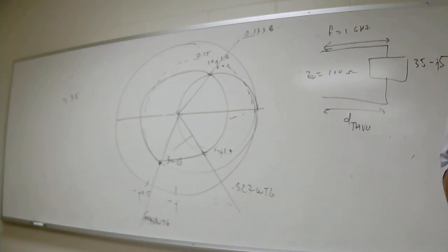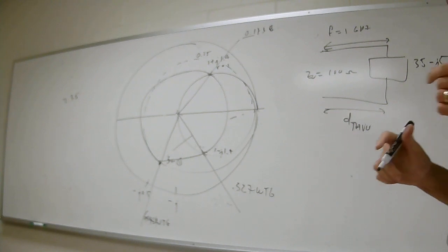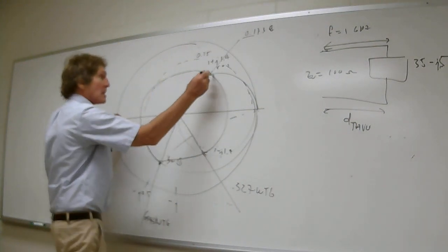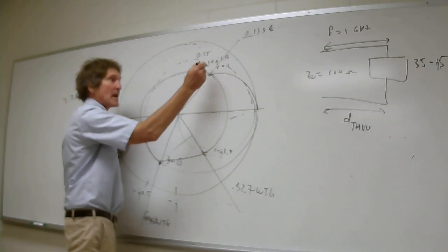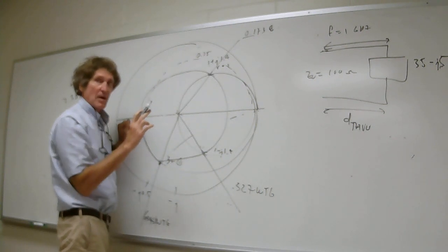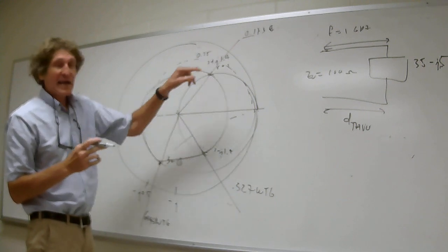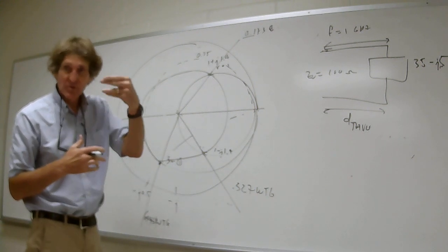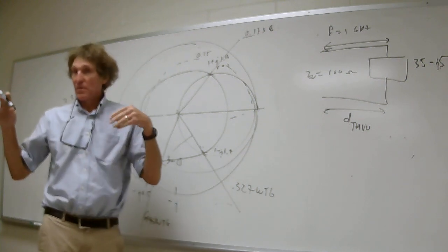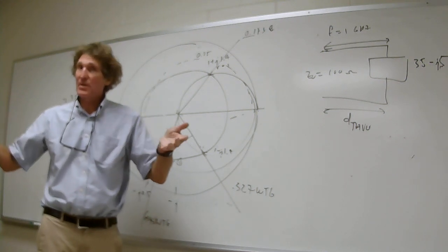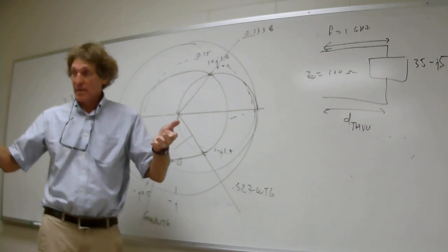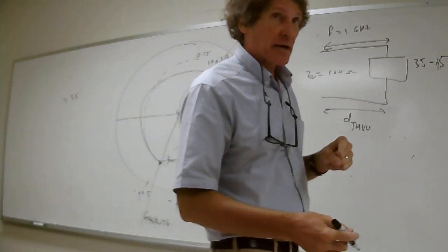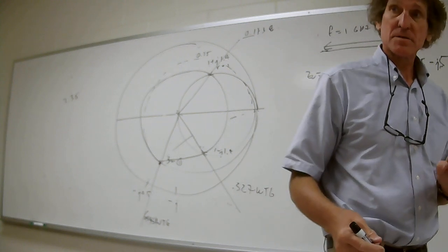Now, think about this. Next thing I want you to take note of. When we're here and we move to here, the normalized reactance is 1 plus j something, right? So to get rid of that reactive impedance right there, we have to add a negative j impedance, right? You all with me? What has a negative j impedance? Capacitor, right? So we're going to add a capacitor. Does everybody follow me on the reasoning, class?